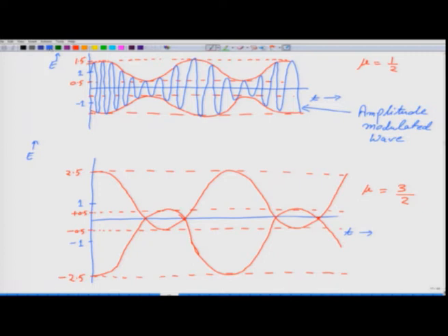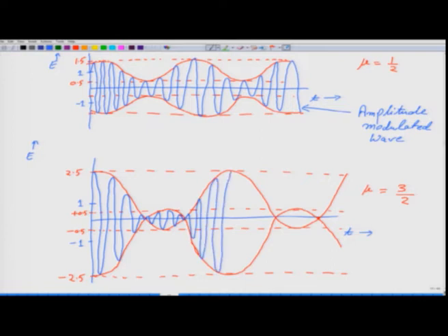And the amplitude modulated wave will now behave like this. So amplitudes are added, so it will start from here, it will come here, then like this, and inside this small band also there will be vibrations. The frequency of the amplitude modulated wave is not going to change, only its amplitude will change, as its name suggests, like this.